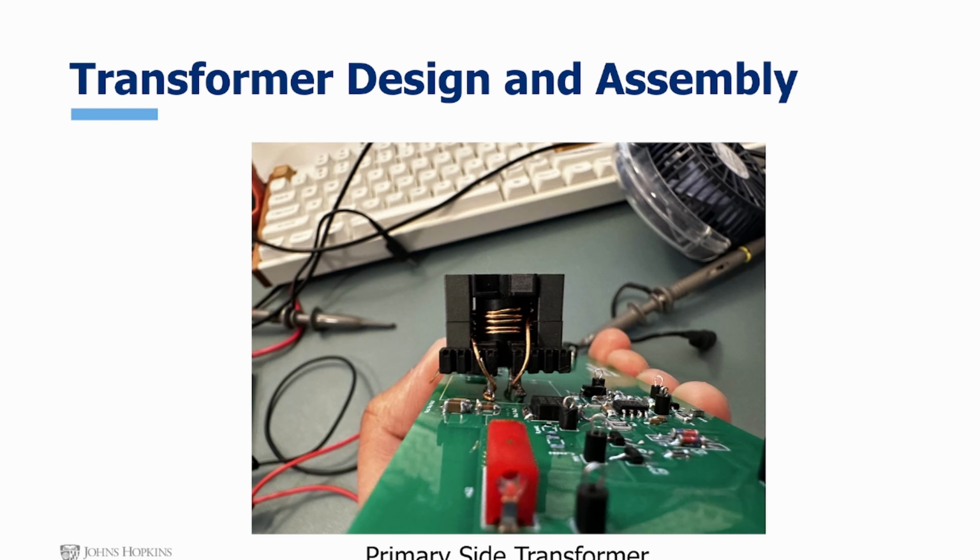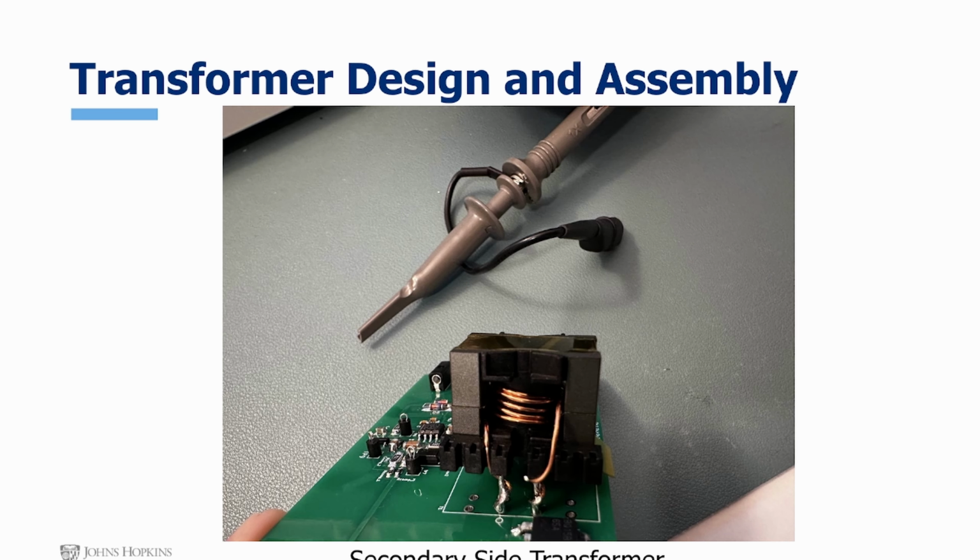This is the implementation of the primary side transformer. I did use a larger number of turns for this, for both the primary side and the secondary side, as the inductance requirement was not being met. At that 2 turns, I had to use a little more as their secondary side transformer.